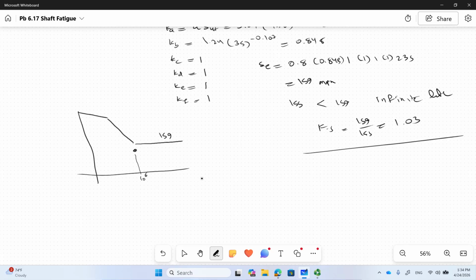If our stress was less than f SUT and higher than Se, then I fall in this region. So if your stress was in that region, then my life is finite, and I know it's going to be less than 1,000,000 and greater than 1,000, because that's what we have.